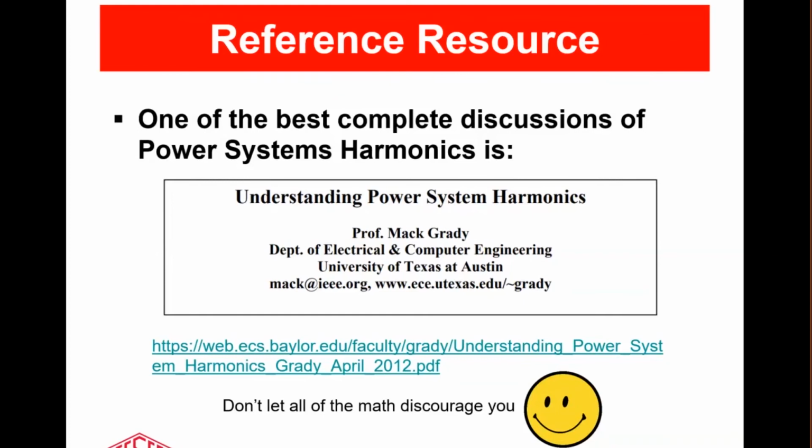So you may have a customer that's only drawing a 25 kilowatt load, and you may have served him with a 30 kVA pad mount transformer, but he may be drawing 100 kVA if he has a really harmonic load.